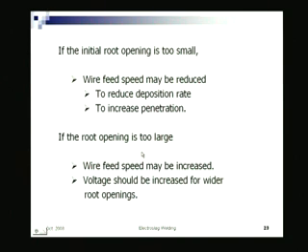No, the whole process is such that we cannot go for very high speed welding. Had it been high speed welding, the case would have been different. It would have opened up, right? But here the very process is such that we cannot have very high speed welding. So, here necessarily the shrinkage is in this direction, that means it closes. So, accordingly you take proper precaution.